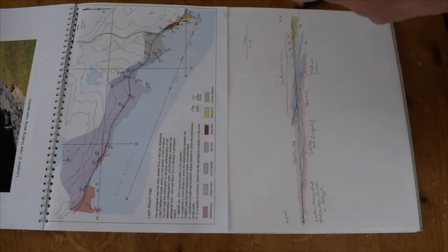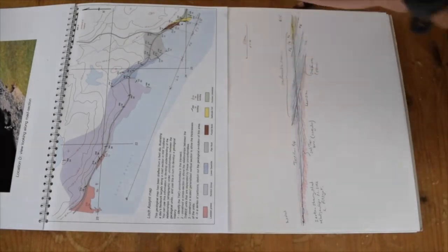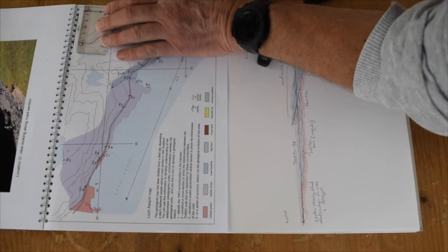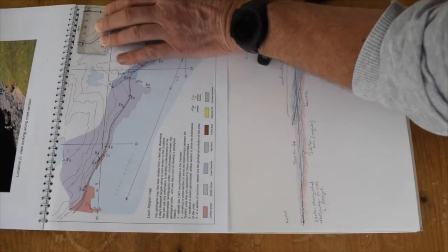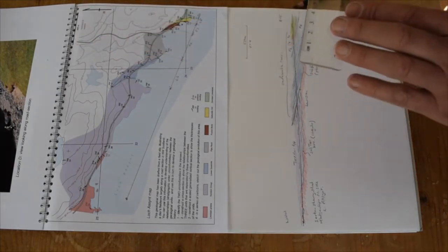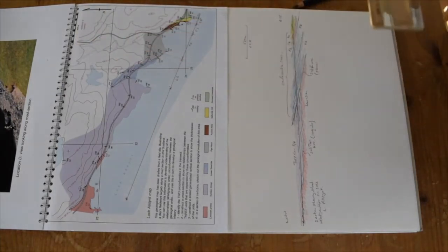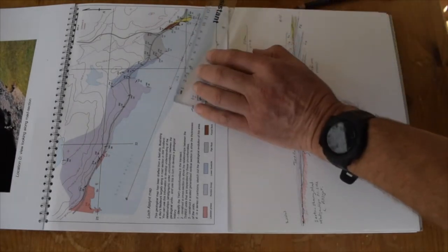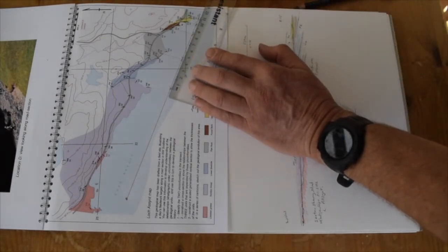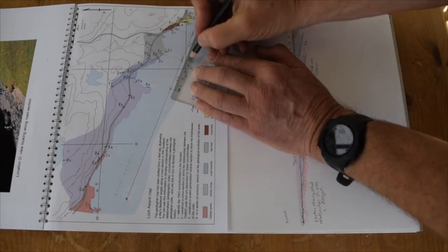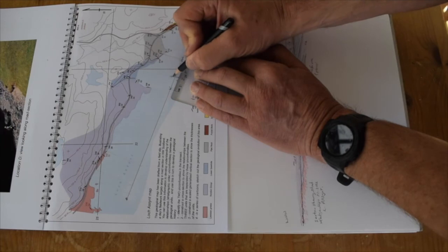So what are these outcrop widths? Well, I'm just going to see what the scale here is. And if I line up my ruler with this, I can see that 500 meters is 5 centimeters on my ruler. So therefore 100 meters is a centimeter. A millimeter is 10 meters. So we can use that directly to make some simple measurements here to get real outcrop widths. So let's do that. The width of the lower quartzite there is going to be 440 meters.